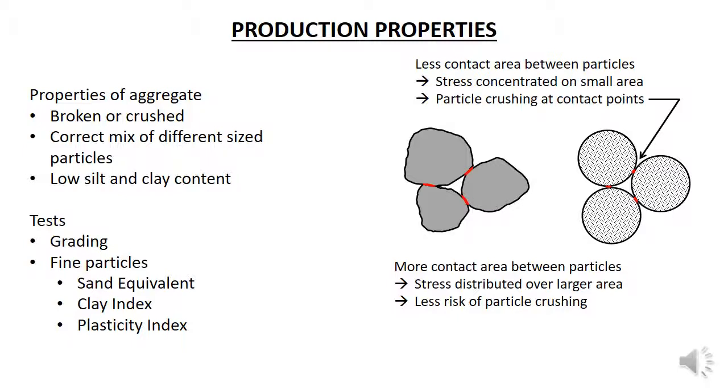The last half of TNZM4 addresses variations in properties of base course from different regions in New Zealand. The requirements of TNZM4 are changed in some areas to allow local rock to be used, and this section provides amended specifications for different areas. It also addresses the use of melter slag and recycled crushed concrete as base course aggregate. You do not need to review this half of the specification, although it may be of interest if you're involved in roading in these areas or if you are using alternative materials.